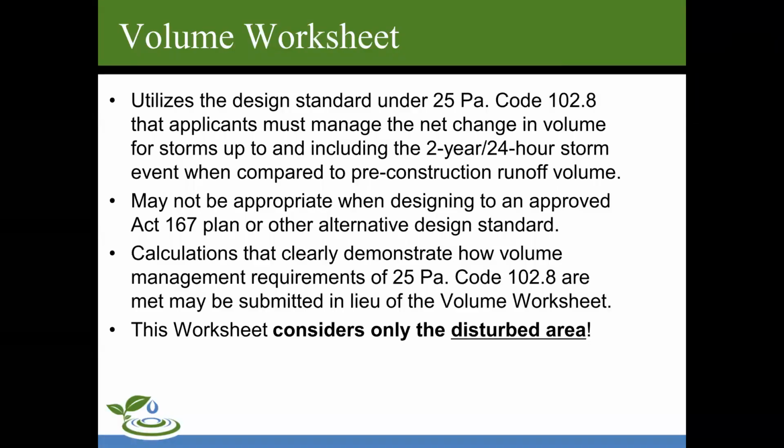The volume worksheet utilizes the design standard under 25 PA Code 102.8 that applicants must manage the net change in volume for storms up to and including the 2-year 24-hour storm event when compared to pre-construction runoff volume. It may not be appropriate when designing to an approved Act 167 plan or other alternative design standard. Calculations that clearly demonstrate how volume management requirements of 25 PA Code 102.8 are met may be substituted in lieu of the volume worksheet. Remember again, this worksheet considers only the disturbed area.